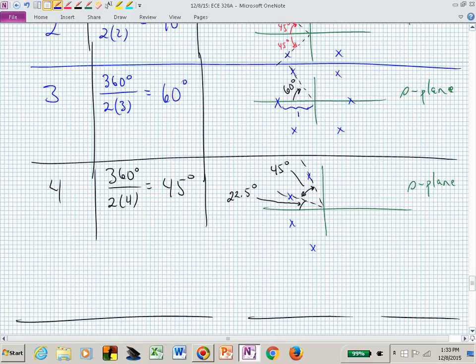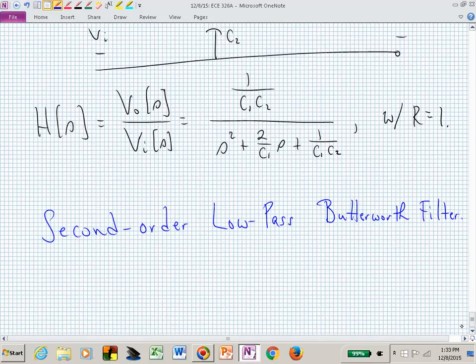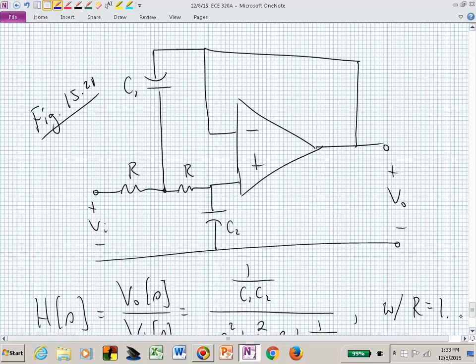We're going to have 2 complex conjugate pairs due to the ones that are closest, and then those further ones give us another complex conjugate pair, and those will correspond to 2 different polynomials in our denominator, and this second order section will allow us to realize those 2 different polynomials. How do we do that?